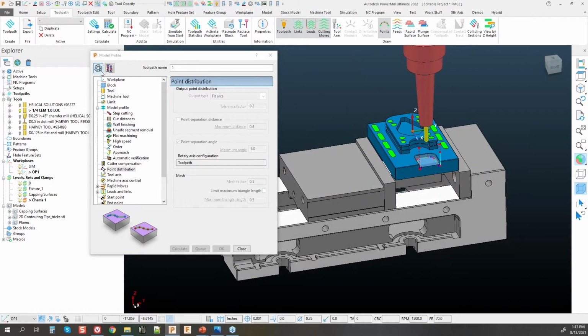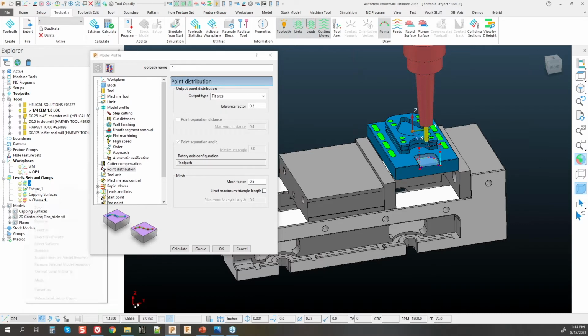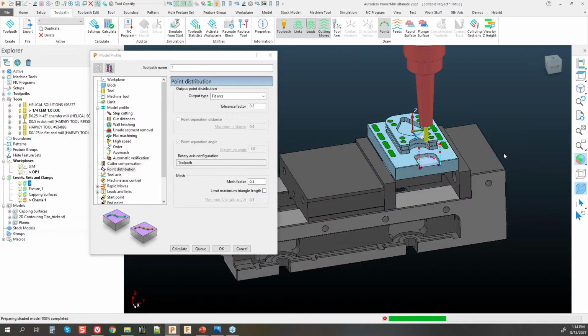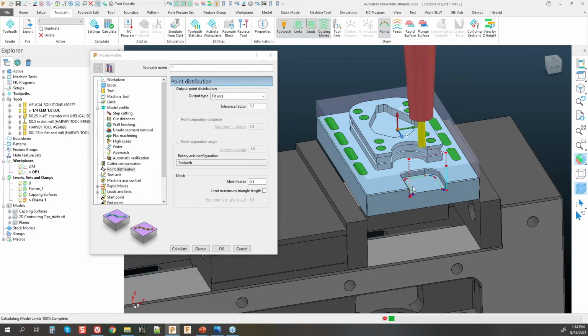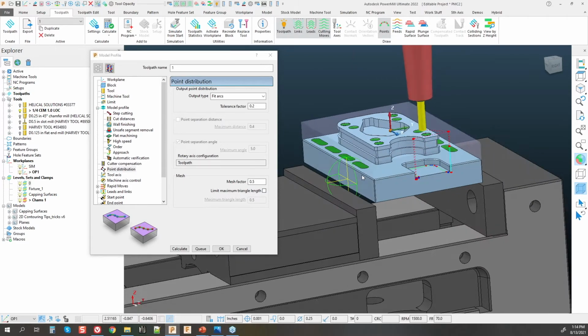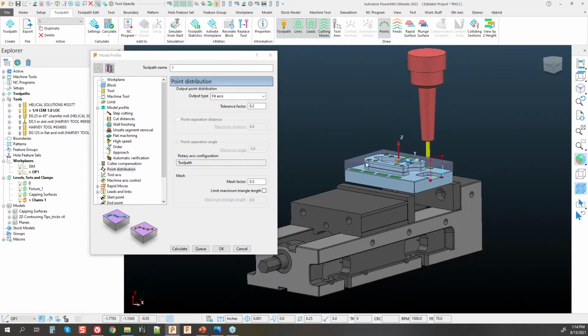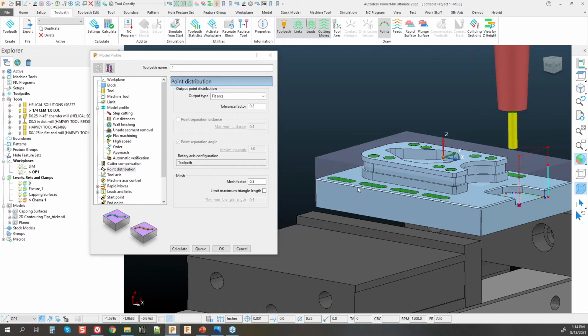I'm going to select my part real quick and we'll just do an entire model profile around this part. Let's go ahead and right click and select all here. And again, I'm just going to shrink wrap a block real quick. That's a special macro that I have that's set to a quick hotkey. That's a command on the tilde, or the squiggly line next to the 1 key. It's actually a feature from another software that I liked that I just applied a macro to. That's how I do that quick block region, if you will.